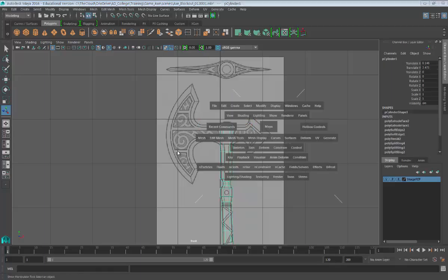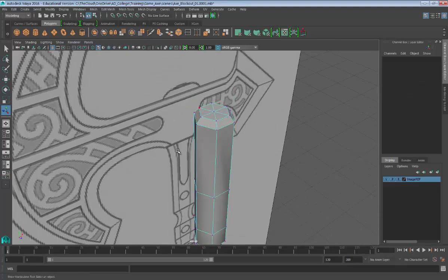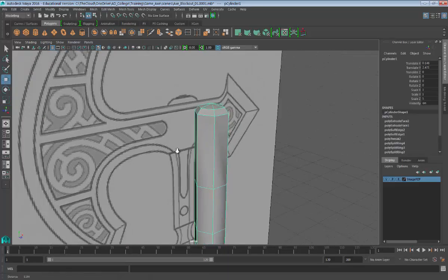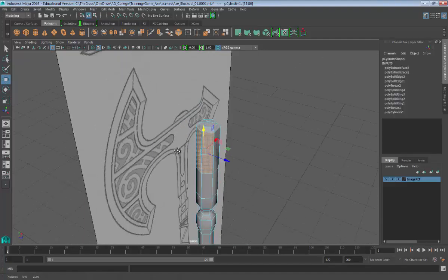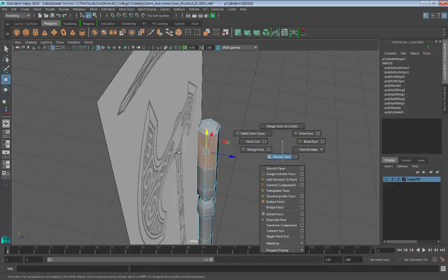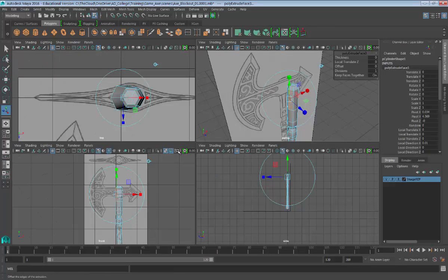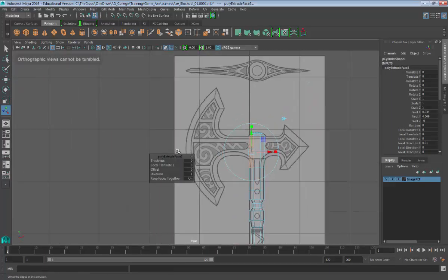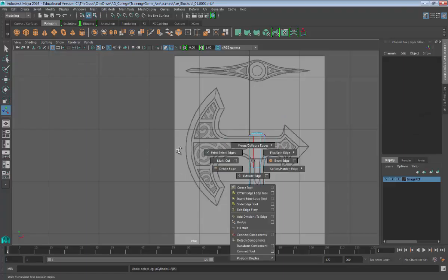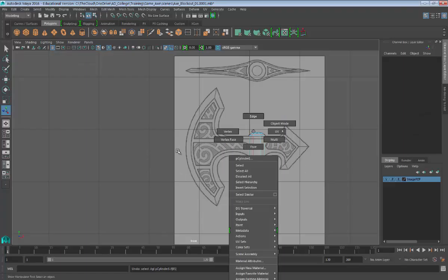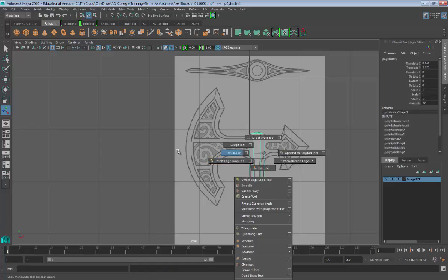And then for the top, because it's slightly rounded at the top, I'm just going to pull out that center vertex. Just put it up a little bit just to give it rounded edges. Okay, I'm going to select the edges now, the faces that I want to pull out. So these are going to come straight out. See, we're just going to pull this straight forward. I can see I need to just adjust the vertex line a little bit as well. So I'm just going to sort that vertex line out.